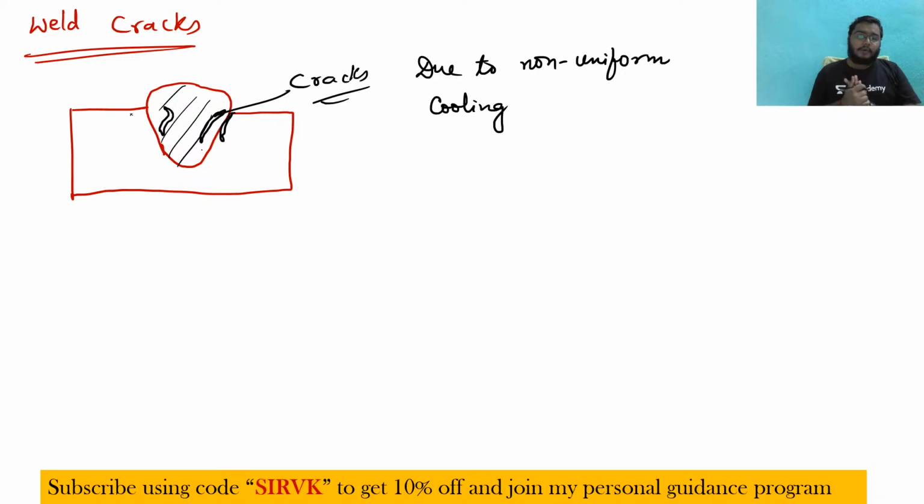Whenever there is non-uniform cooling, internal stresses can be developed. That internal stress stays inside, so that is a residual stress that will form. Now when this stress tries to relieve itself, it will form a tear, it will produce a crack in the weld bead.